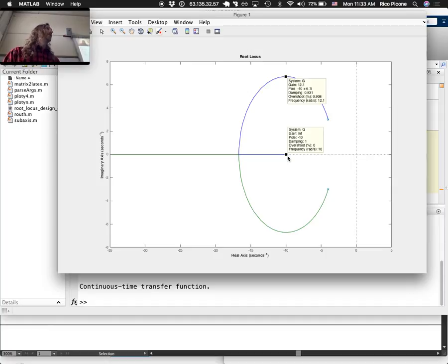So we could also get that transient response requirement if we turn the gain to infinity. However, that's going to require a control effort of infinity, which is not a realistic amount of control effort. So if you multiply your error by infinity and you try to supply that voltage to a motor, you will fail, I predict.